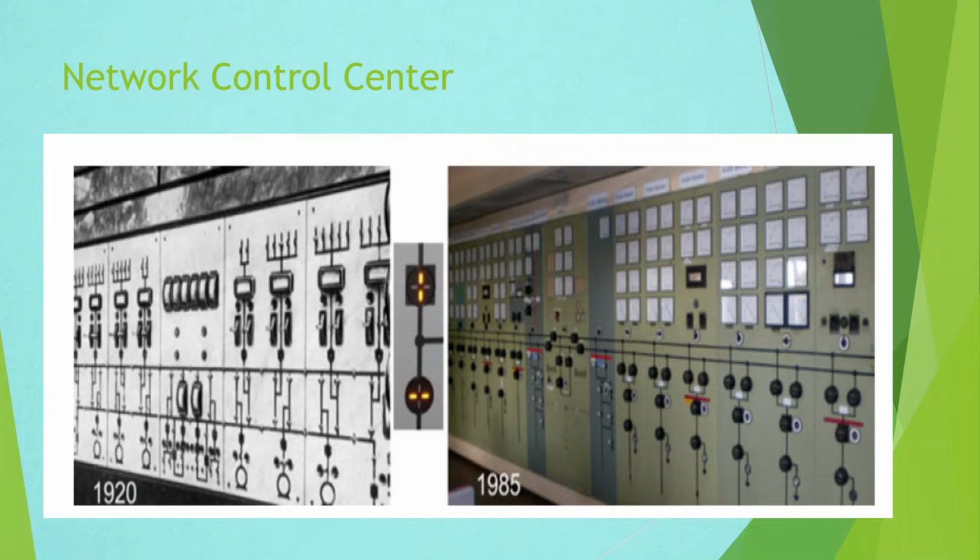The substation control level provides an interactive workplace for the operator with control and visualization elements. Here, the scheme of the whole substation is available. Events are signaled and measurements can be monitored. It is possible to control all parts of the substation. The substation interlocking extends the bay interlocking from a higher point of view. For example, an isolator can be operated if the related circuit breaker is switched on, but the topology of the substation scheme shows that there is no current.